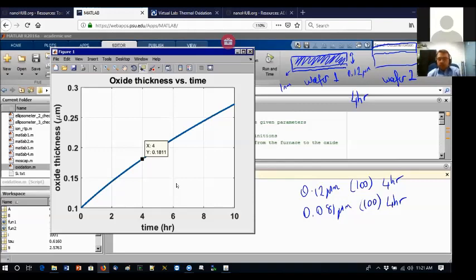So, why did we grow less? Actually, we already discussed this. We grew less because the oxidant coming from the top was having a difficulty to penetrate the whole thickness here. So it's going to grow less at a slower rate. That's why if you have an initial oxide, the end result will be different, and it's not a linear system. That's what I want to emphasize. It's a nonlinear output.